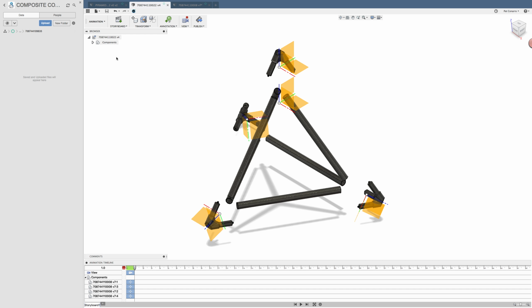And then that animation's done, and then I can go create a drawing from animation, and I click on it and I go, yeah, let's do this one right here. I could have you make us a template, create a new drawing, and we can just say this one here, length times width, and I click on this and I say OK, and so now it'll bring the exploded view into the drawing, and so I need this drawing created.